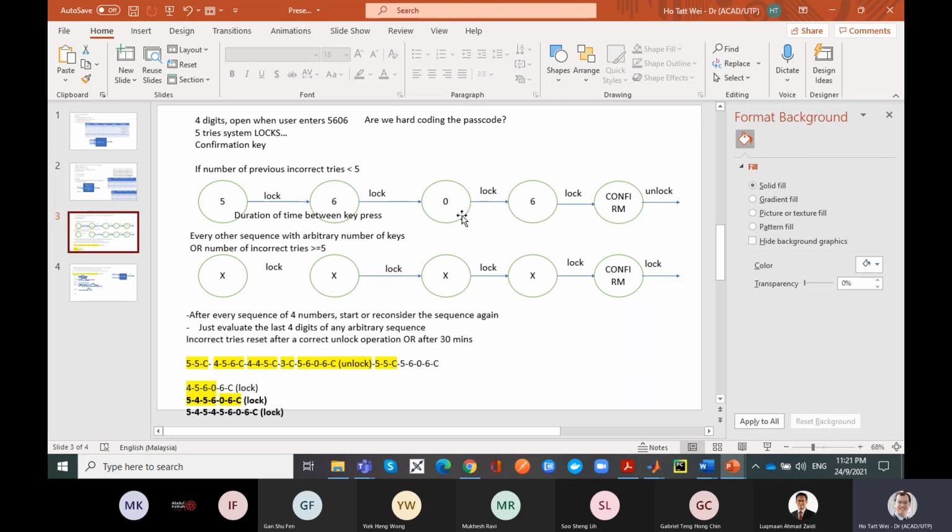Let's say you want to add two 64-bit numbers. If you want to completely specify all the input combinations, you have 2 to the power of 64 times 2 to the power of 64 possible input combinations on the data path. You don't do that. You say this is the data path. There's any arbitrary number. There are 2 to the power of 64 combinations of number A and number B. What I do is I add them together, and the add operation is like you have a separate table that you can actually show what it is.